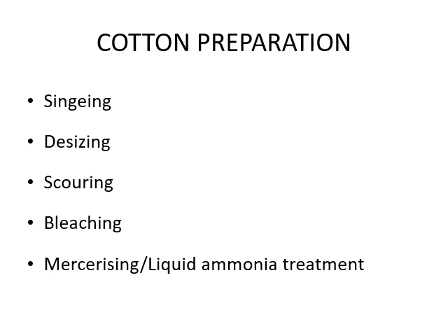Woven fabrics also require sometimes singeing prior to desizing. Also, many end products are required to have very high whiteness in order to be printed, dyed to light pastel shades or to be sold as a market white. Preparation processes must be carefully controlled to minimize fiber damage, which can lead to the fabric yellowing or even strength losses.